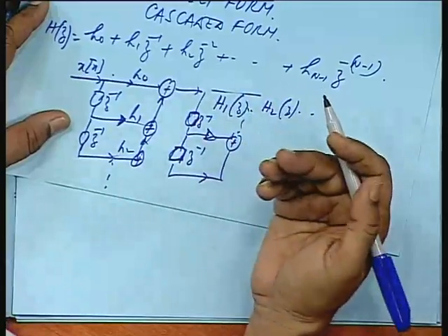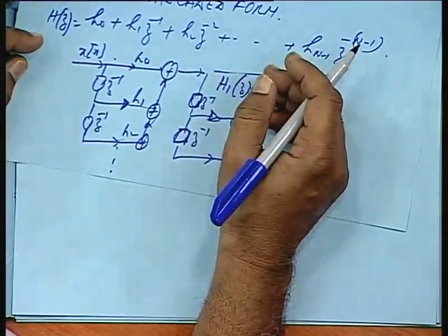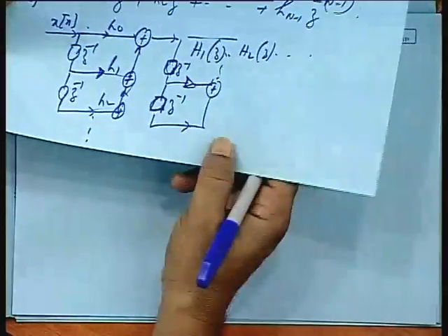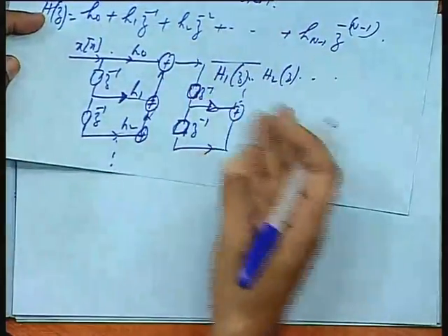Parameter values change because of truncation: you have a finite register length, an 8-bit or 16-bit register. So, all these coefficients will be truncated, either you round off or you truncate. So, there will be some error, all right. These errors will have some effect on the location of zeros. So, anyway, this is the direct form and the cascaded form.